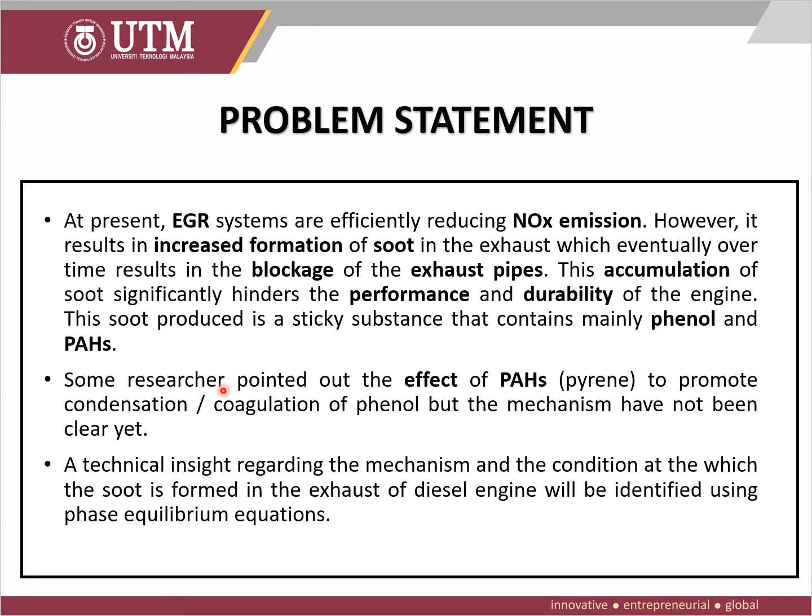Some researchers pointed out the effect of PAH to promote condensation and coagulation of phenol, but the mechanism has not been clear yet. Technical insight regarding the mechanism and the condition at which the soot is formed in the exhaust of the diesel engine will be identified using phase equilibrium equations.